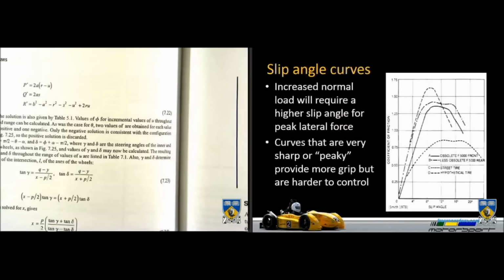and you can think of that as generally a tyre's lateral performance. So if you have the really peaky tyre, the one that's got the highest coefficient of friction, about 1.6 or something like that, you'll find that at whatever it may be, 6, 8 degrees of slip angle, it's not too bad. It's really good compared to the other 3 tyres that are on there.